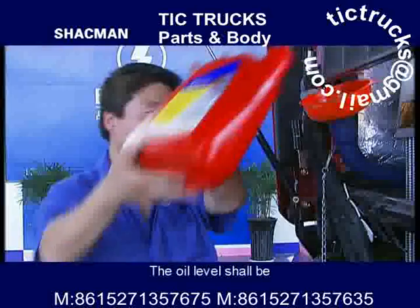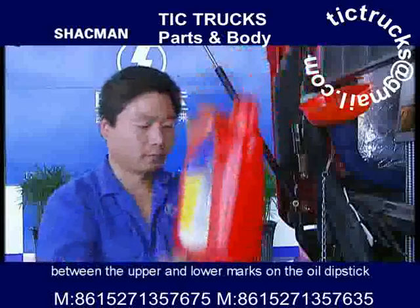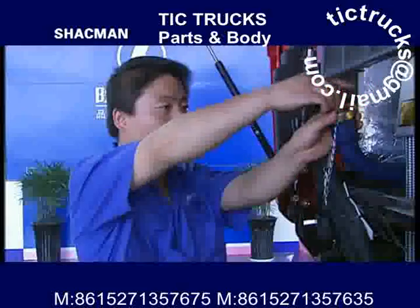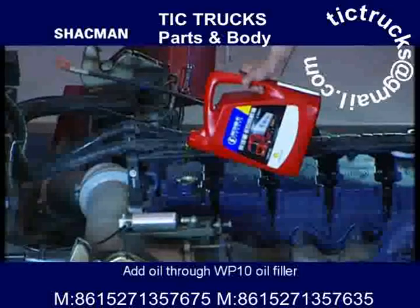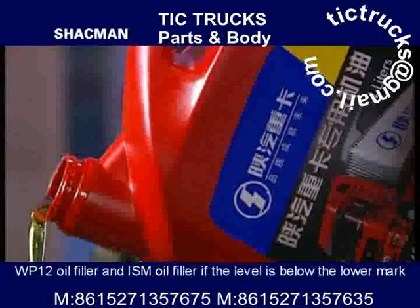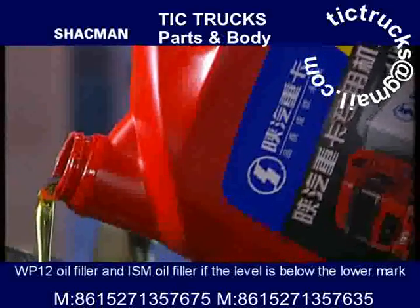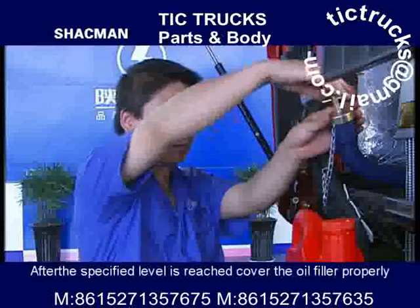The oil level shall be between the upper and lower marks on the oil dipstick. Add oil through WP10 oil filler, WP12 oil filler and ISM oil filler if the level is below the lower mark. After the specified level is reached, cover the oil filler properly.